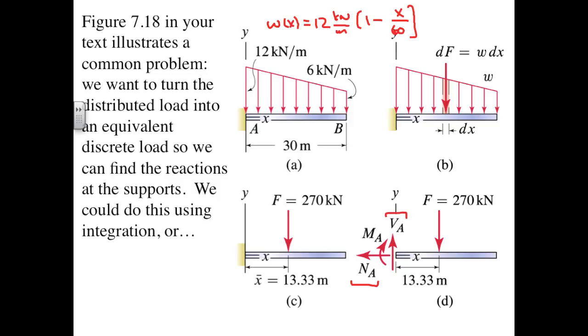The moment reaction has a familiar label. It is also transverse to the long axis of the beam, although it's in the z direction instead of the shear force's y direction. This moment is referred to as a bending moment because of the kind of deformation it tends to induce in the beam. These labels reflect different kinds of deformation associated with these different loads and become important both in Chapter 8 and in the transition to deformable bodies in mechanics of materials.